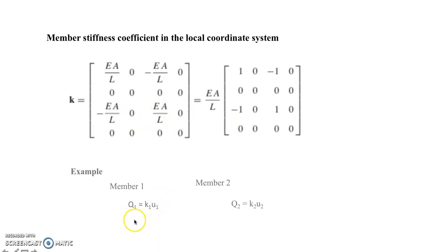So then afterwards, once you have the value now for Q, for K, and for U, you simply have to simplify the equation using operations of matrices, and you can solve now for the value for Q, and whatever you have simplified corresponding to that, for every member you have 4 Q: Q1, Q2, Q3, and Q sub 4.